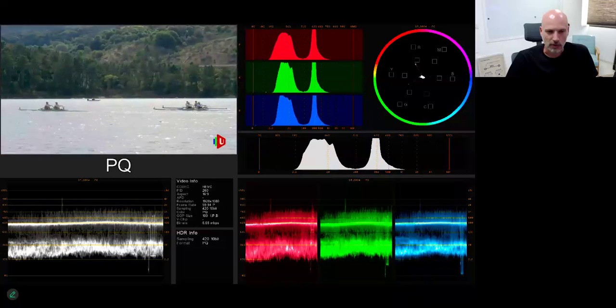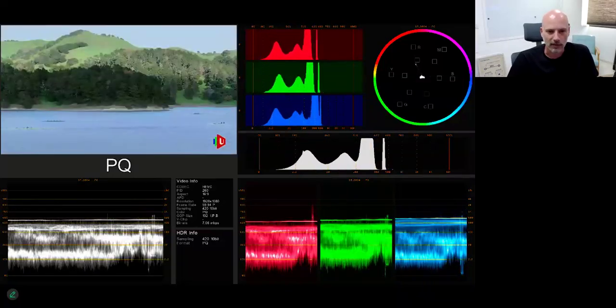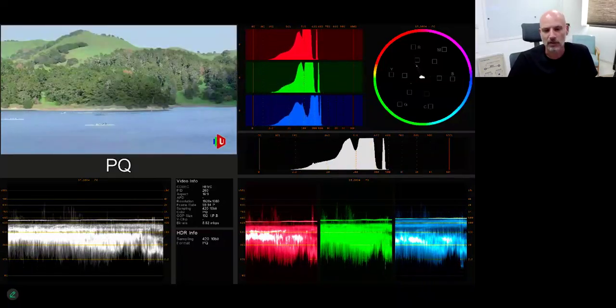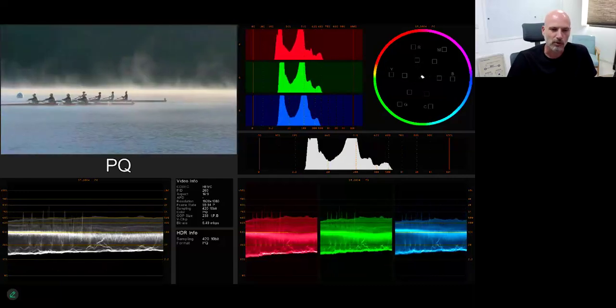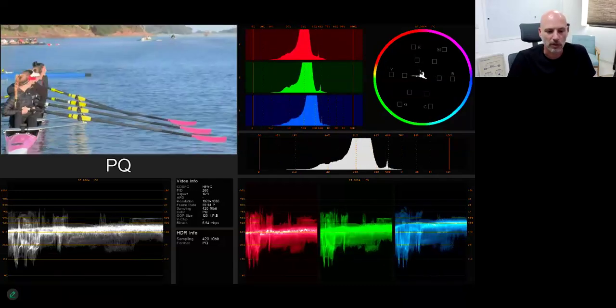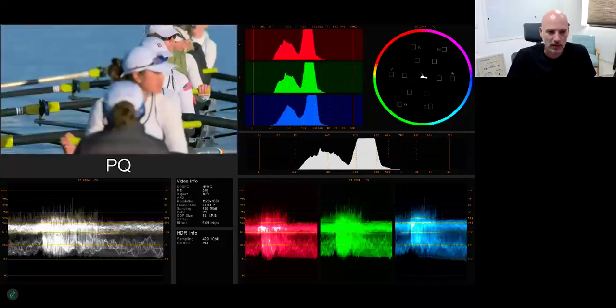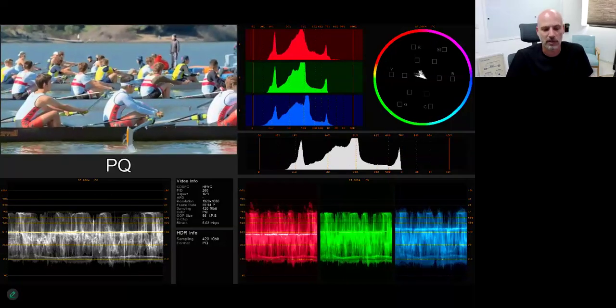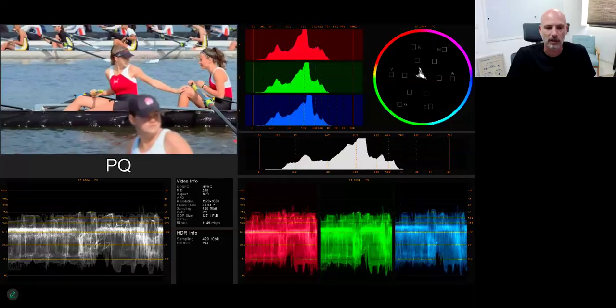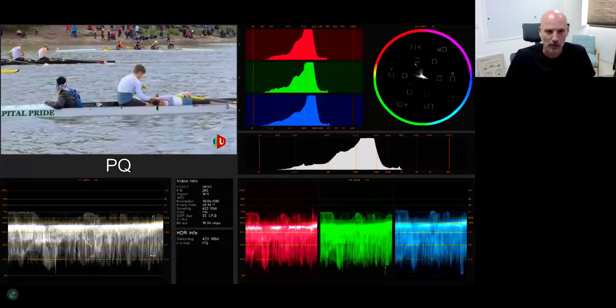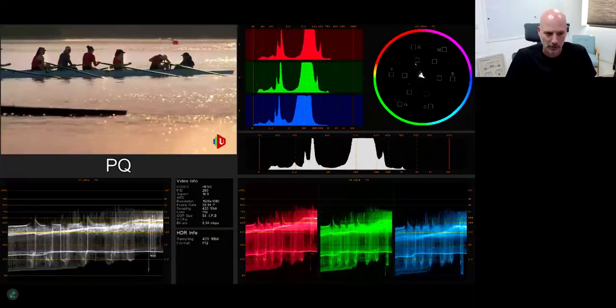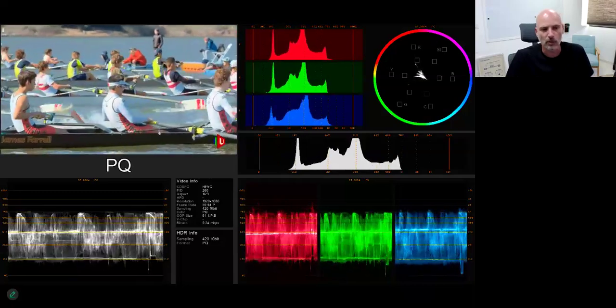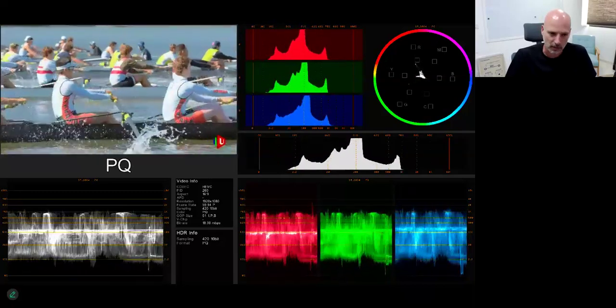It's an excellent question. If you're talking about 2110, in 2110 nothing is encoded along with the video. So you have the 2110-20, which is the pixels themselves. Even the color space, SDR, PQ, HLG, is not defined in the stream. It's defined either in the SDP file or in the -40. The -40 is the place where you hold the metadata.